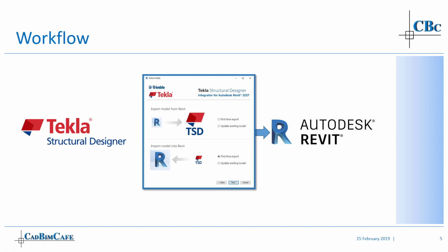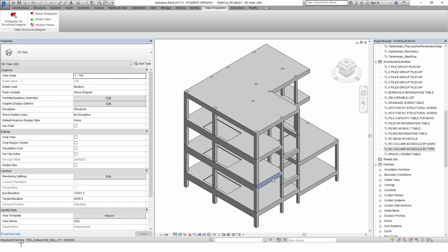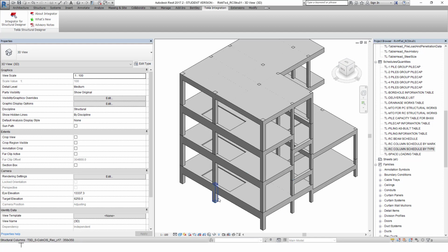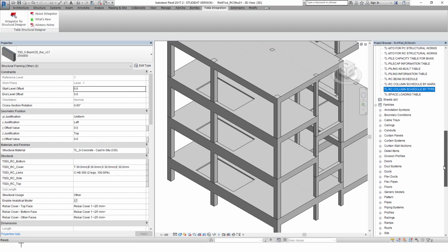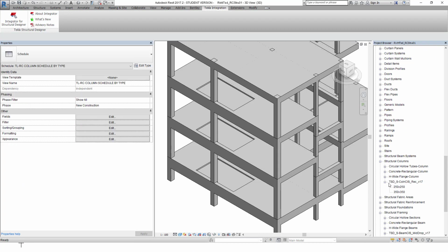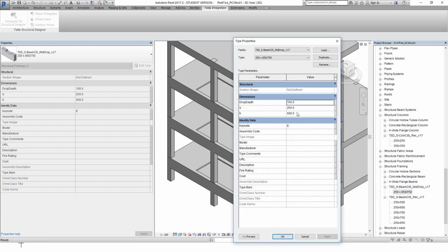Then lastly, I want to mention is that, for example, in Revit, some points we need to drop the beam. Then what we need to do is, after settle it, we go and select the beam, and we purposely drop it. For example, this beam is not 850, right? So we have to create the same size in the other family. Currently is only one family or two family. Okay, we have this family there, so we have to rename it. This one to be like 850 by 750. Then this beam will be 850, drop 100, so 750.